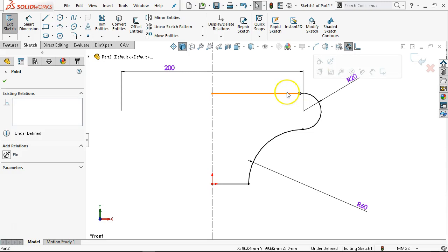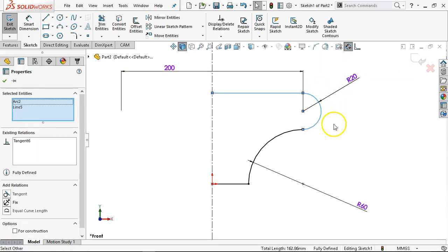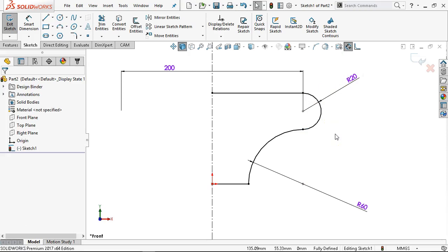It's probably one of the things that you will pick up most often, because this was a continuous tangent arc, and I pulled the next arc off tangent as well. I kind of expected this to be tangent, but when I highlight, I'm not seeing a tangent symbol. So select, control select, tangency, and that'll go defined. Let's see, those are going to be